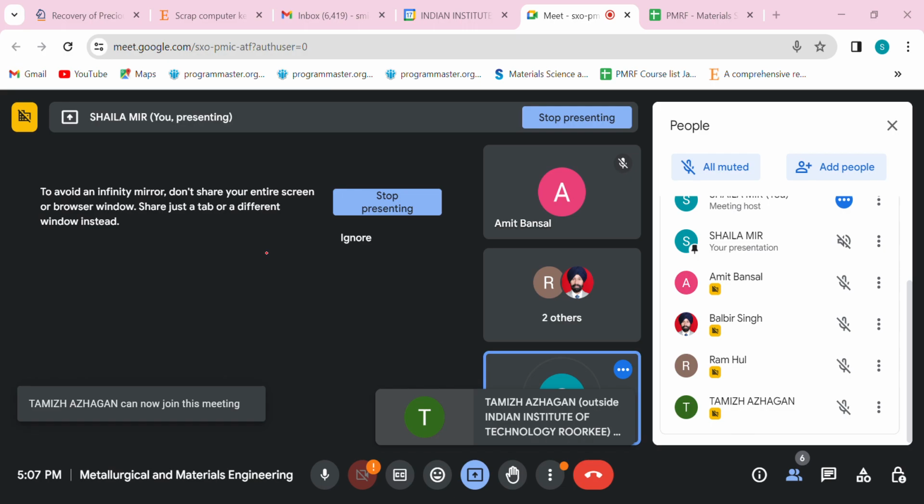Ma'am, I have a question regarding creep. In some books, it is said that creep can occur even at normal temperature if we stress the material for a longer period. Is high temperature necessary for creep to happen? For creep to happen, you should have very low strain rates. Mostly the concept is of strain rates, but we tend to expect it in the form of temperature also. Even with low strain rates, if you have a material under constant loading, creep can occur. It depends on the material.